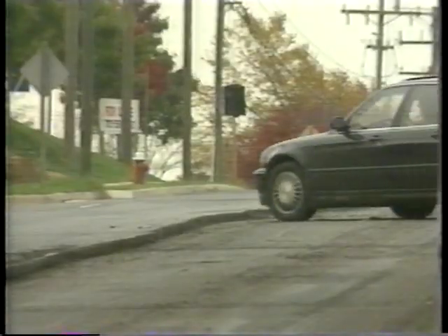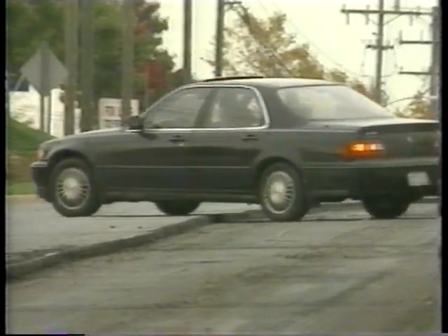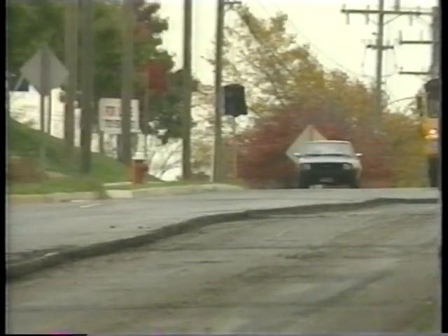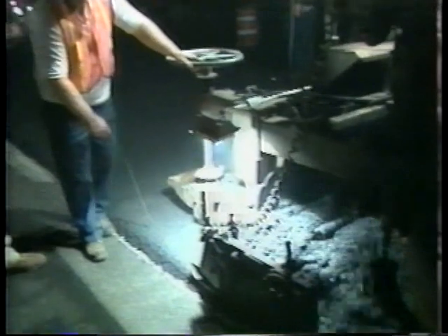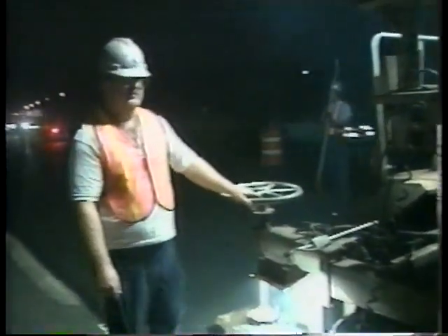A difference in elevation between two lanes or a lane and the shoulder is called pavement drop-off. This situation requires some special attention. There are several precautions to take. Avoid drop-offs greater than 5 centimeters left overnight and immediately adjacent to traffic. They have a high accident potential. Specify that the contractor schedule resurfacing or construction operations so that no drop-off is unprotected overnight.